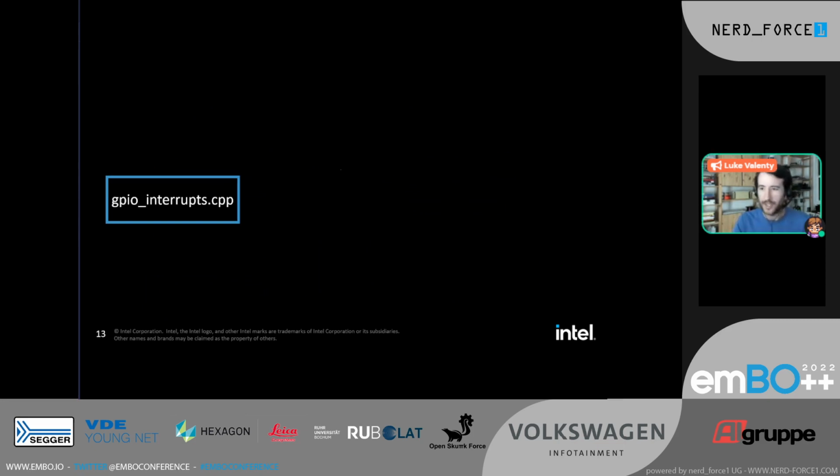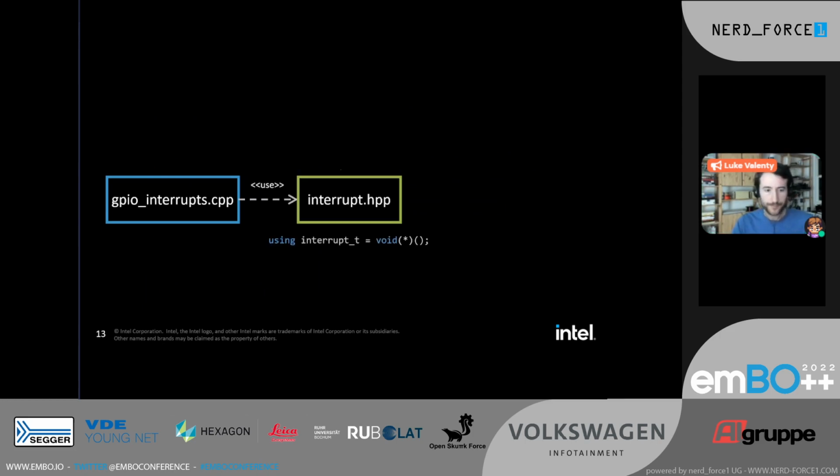What does this look like in practice though? Like how do we actually implement the dependency inversion principle from a generic standpoint? Well, let's say we have our GPIO interrupts service. And this is going to be a service that can call something whenever a GPIO interrupt is triggered. Instead of GPIO interrupts depending on the features, it's going to depend on a generic interface. And that generic interface, in this case, is a simple function pointer.